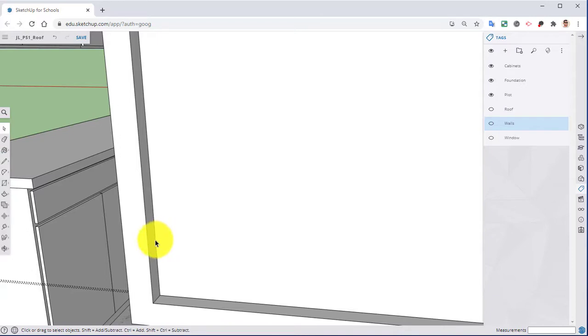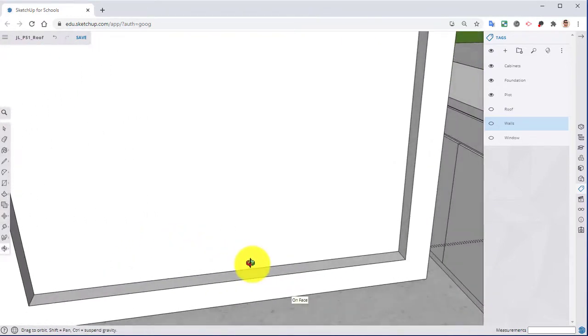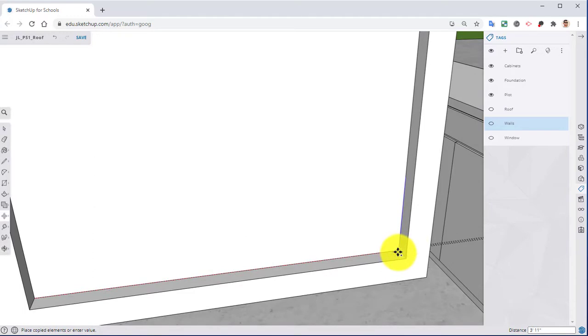Next, take your selection tool, click on that line, take our move tool, click on it, hit Control to make a copy, drag it all the way over to the right side, click, then type /3 and hit enter. Actually, let's do /4, in order to create 3 spaced out centered lines.